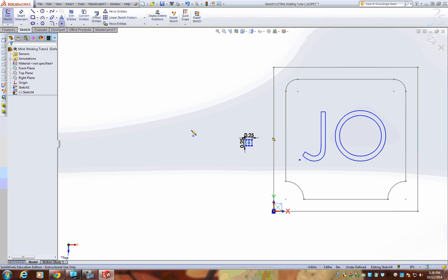We're now going to place this object at 12 o'clock and 6 o'clock of that O. Again, that's going to make sure that that O stays an O. Otherwise, when you cut, it'll just be a hole, and that center part will just drop out.